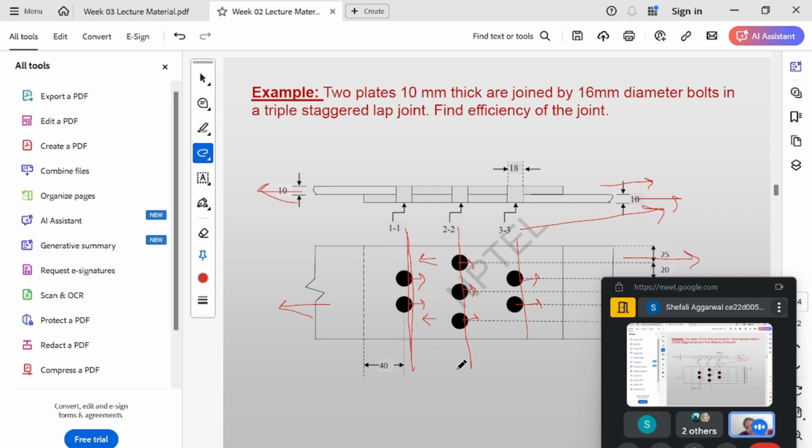It is failing without failure of plane 1 bolts. I mean, if the plate is failing at the plane 2 section, there cannot be any case where that is possible without failing the bolts in plane 1-1. No, there won't be a case. If plane 2 is failing, there is a high chance plane 1 will be failing along with it.